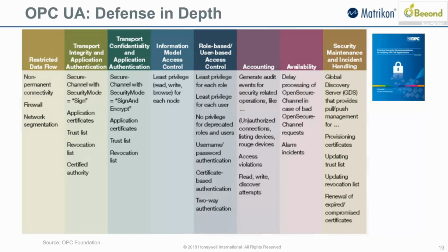But basically, it goes through and identifies some of the things that OPC UA does that's just built into the spec, that's expected from an OPC UA server to ensure that things are kept secure, that the system stays trustworthy. So whether it's how efficiently the server discards packets that are malformed, so it's not trying to decrypt packets that are bad, purposely malformed for example in a form of denial of service attack,